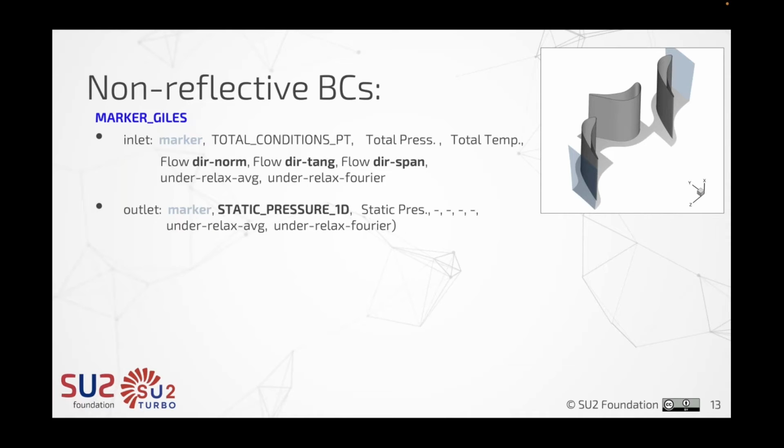So when do you have to use one or the other? When we run calculations for an axial machine, we have something called radial equilibrium, which requires the flow elements to be in radial equilibrium, meaning that the radial forces are balanced. Because of this, without going into the details, you will have a distribution of quantities from hub to shroud.